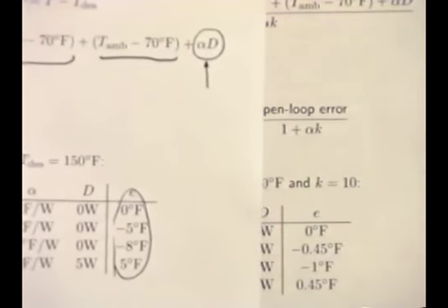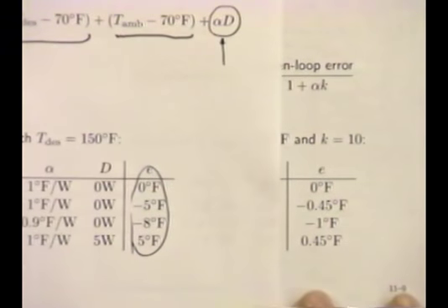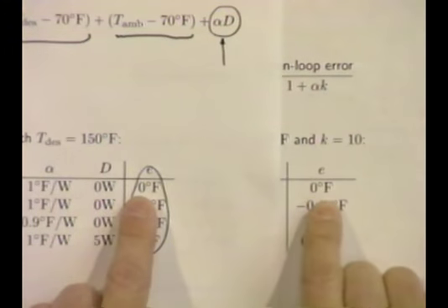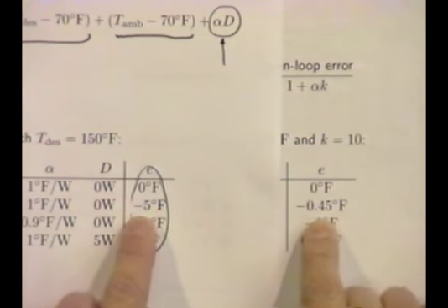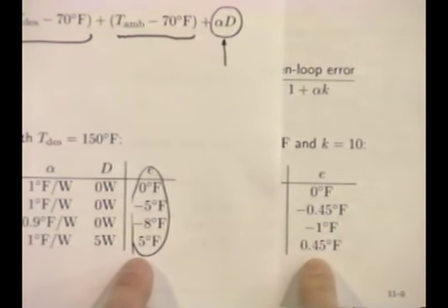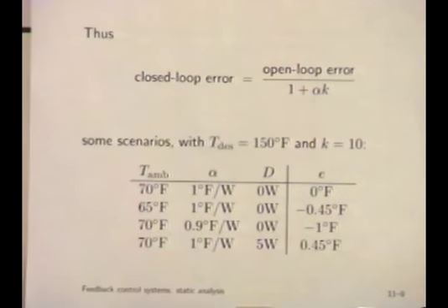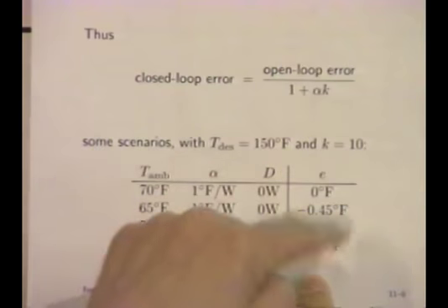So if you were to compare these errors, here they are. Okay, if everything is what you think it is, the closed loop system works no differently, no better, no worse than the open loop system. But now start comparing these numbers. They're all divided by a number that's around 10. But that's around the loop gain here, right? So these are spectacular, these improvements.